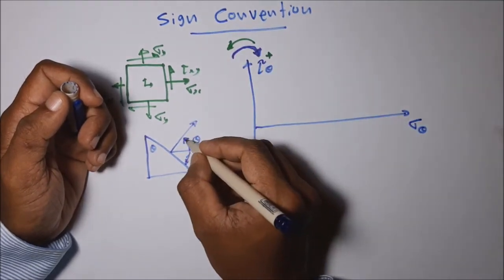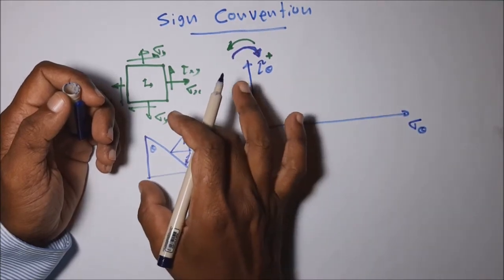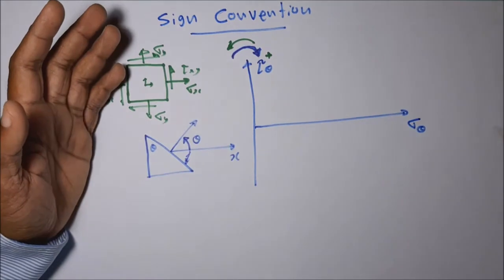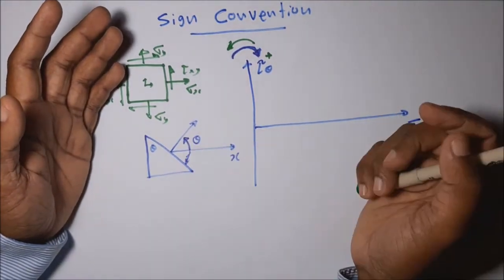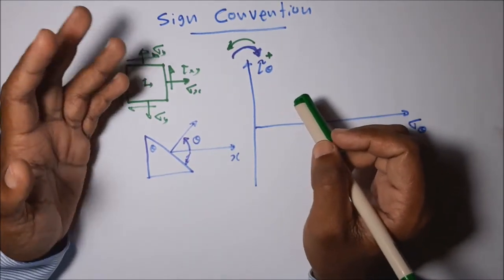To make this angle measuring direction the same as the Mohr circle diagram and also the two-dimensional planar diagram, then we can easily calculate. There's no confusion with the angle measuring direction. This is one of the reasons we take this clockwise shearing stress as positive.